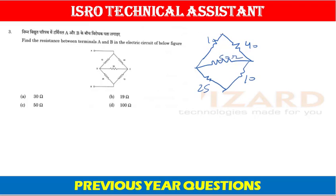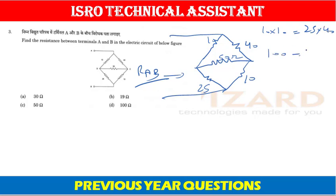We have to find the equivalent resistance between A and B, that is RAB. First of all, we will check whether the bridge is balanced or not. 10 into 10 is equal to 25 into 40? 10 into 10 is 100, but 25 into 40 is 1000. Therefore, the bridge is not balanced. This means that current will flow here.